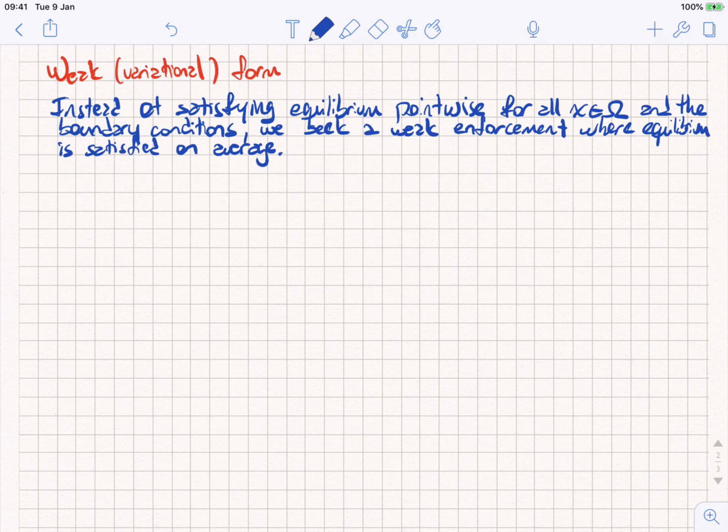Okay. So we are already almost in time, so let's extend a bit so that we treat the weak formulation. Okay, let me just write down the expression and then we go to the break. So what I said is we take our differential equations, right? So it's EA d²u/dx² plus B minus KU.